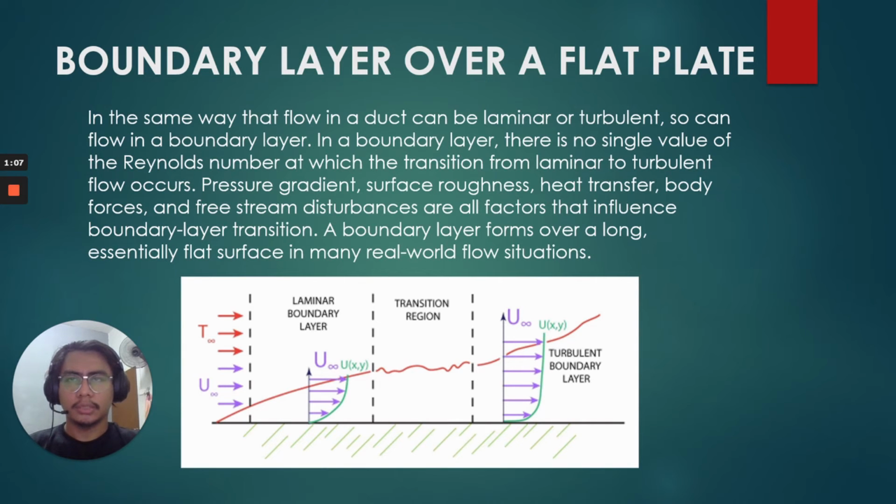The figure below shows a qualitative representation of boundary layer growth on a flat plate. The boundary layer is that portion of fluid flow near a solid surface where shear stresses are significant and the inviscid flow assumption may not be used. All solid surfaces interact with viscous fluid flow because of the no-slip condition, a physical requirement that a fluid and solid have equal velocities at their interface. Thus, a fluid flow is retarded by a fixed solid surface and a finite slow-moving boundary layer is formed.